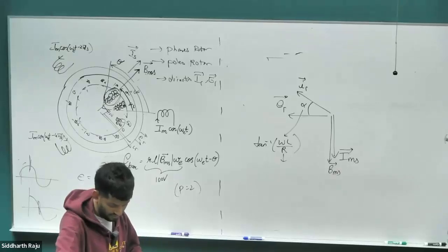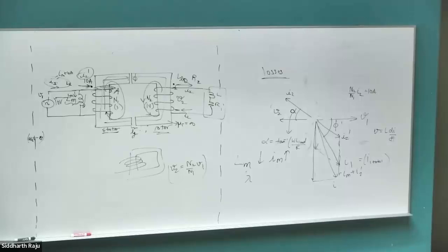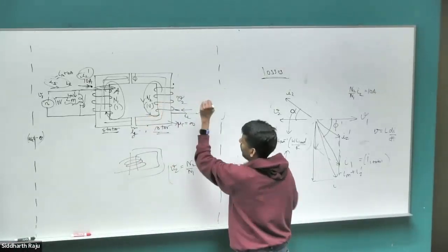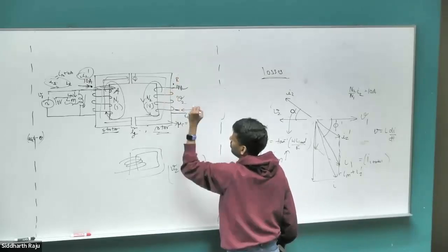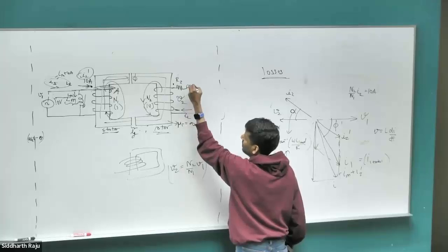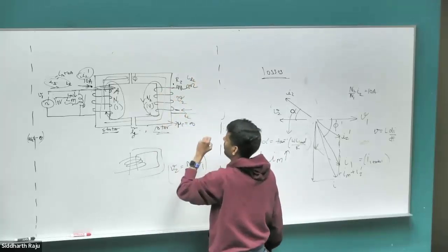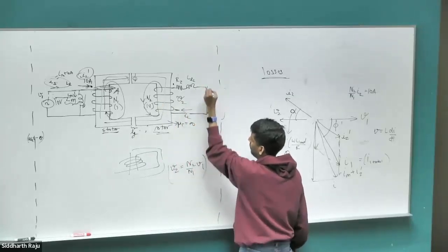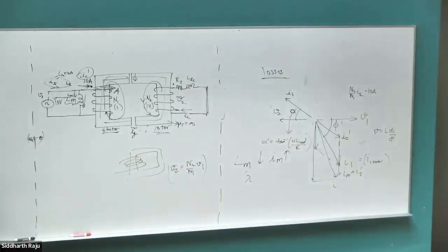Leakage, perfect. So going back to the transformer model, in the case of an induction motor, what changes is that instead of a load, we have some resistance due to the coil itself, and then some leakage inductance due to the coil again, right? Because the flux is leaking on the rotor side without leaking on the stator, and then this part is just shorted out. That's what our end rings are effectively doing for us, shorting the whole system together.